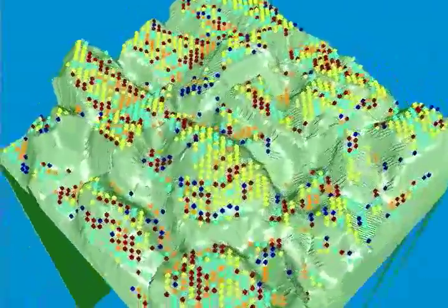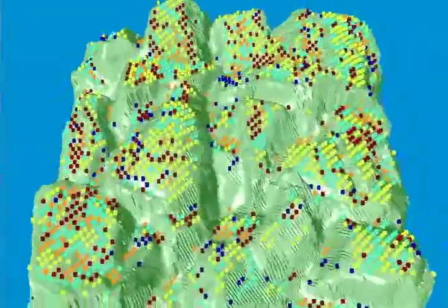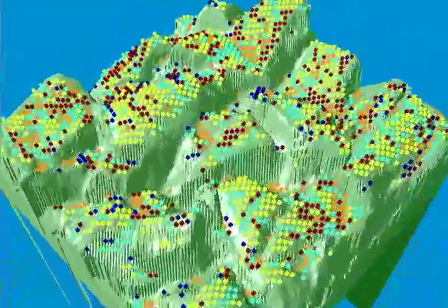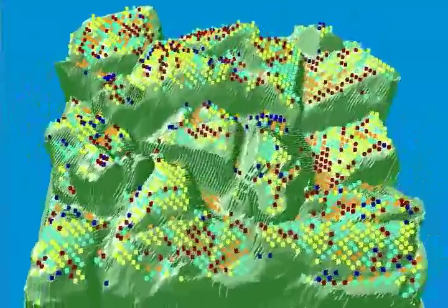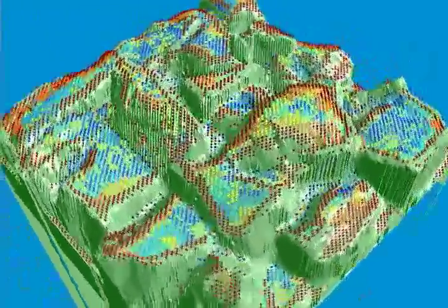While this method provides information on local terrain data, it fails to capture large-scale properties such as proximity to drop-offs. When a heuristic drop-off score is added, the final cost map can then be used to choose footsteps in a path planner.